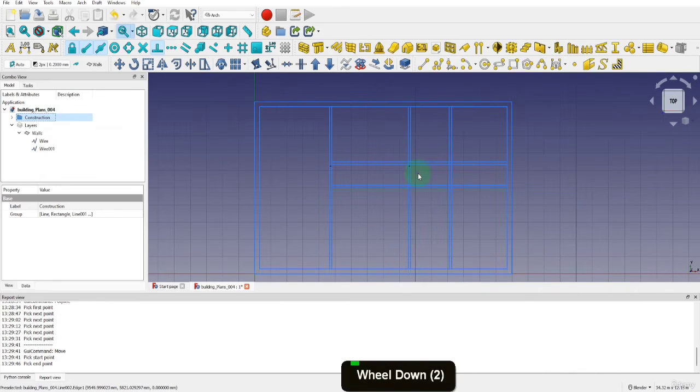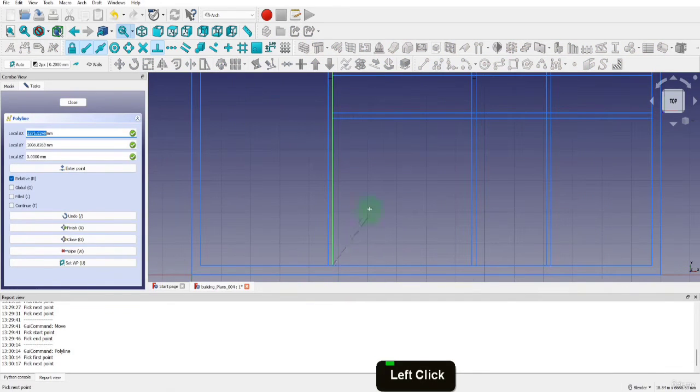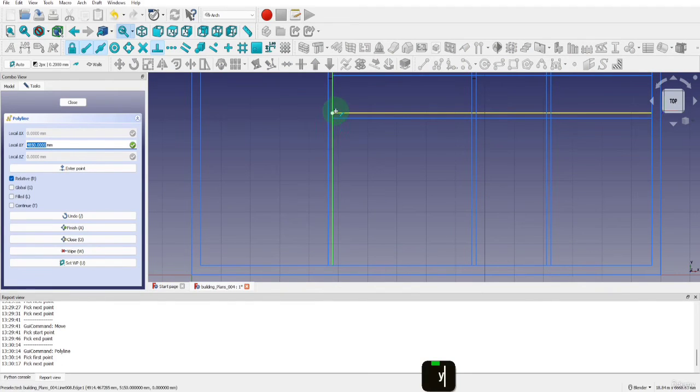We can now create the bottom sections to match the top. So select the wire tool again. Select the second point on the bottom to get the base point. Now drag up and press Y to lock in the axis. We can hover on this endpoint and get the distance. Drag up and input 100 and enter.